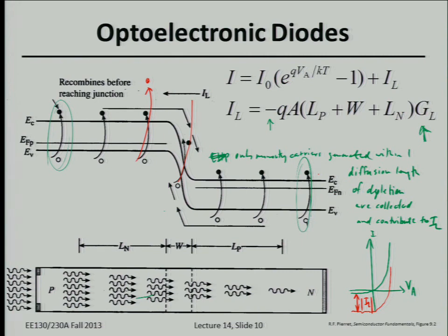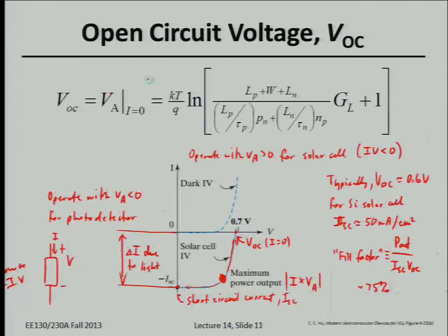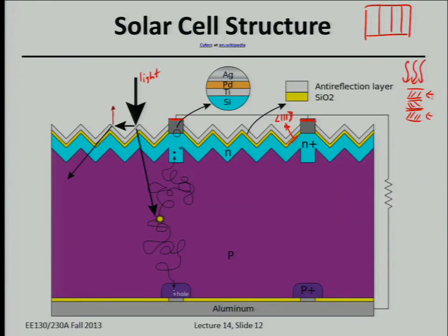So you basically want to absorb the higher energy photons first with the larger band gap solar cell up here. So you want large EG up there and the smaller EG down here, so you can efficiently absorb the photon energy across different regions of the solar spectrum.